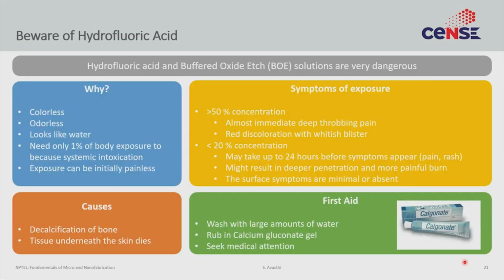Finally, a topic on hydrofluoric acid. It is by far the most dangerous acid that is probably there inside a clean room and must be given respect. It is very dangerous partly because it's odorless and colorless, so it looks like water, and has the viscosity of water. Often we are using dilute HF solutions, which are mostly water, but it doesn't take a lot of HF to cause a lot of damage. Your body needs to be exposed at only 1%, which you can imagine is maybe just a small area on your body, to create an exposure that is potentially toxic, potentially life-threatening. So one drop, a little bit of spill, is enough to cause a lot of problems.